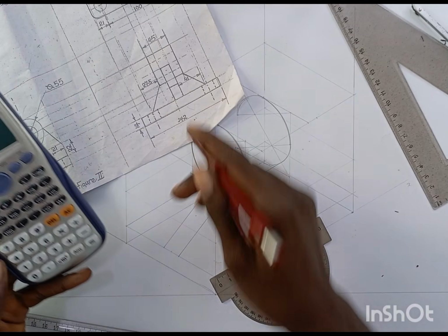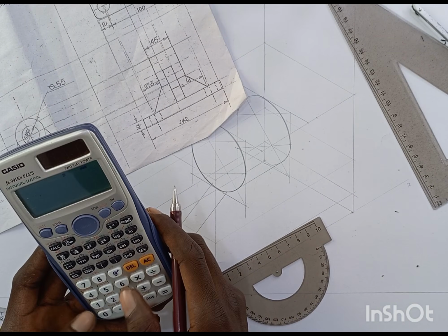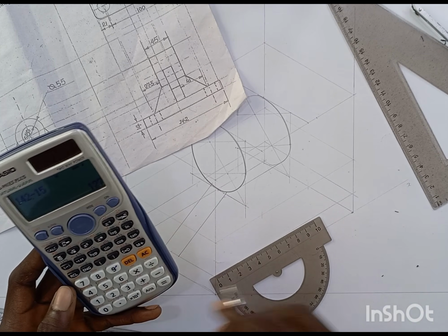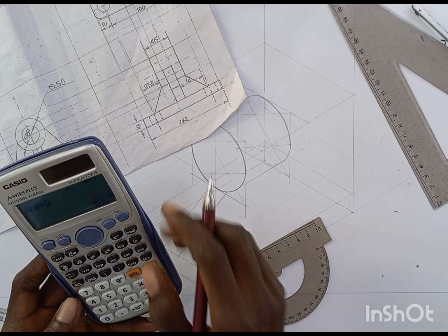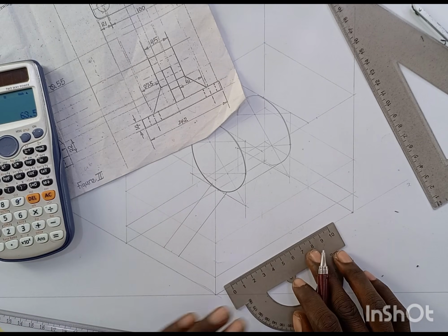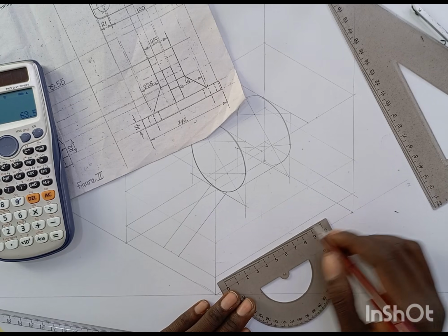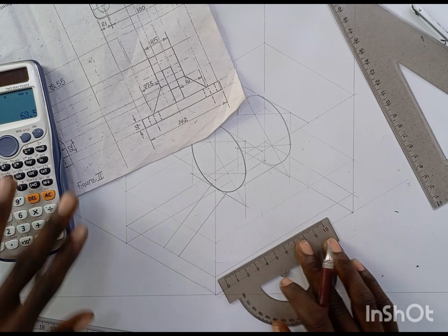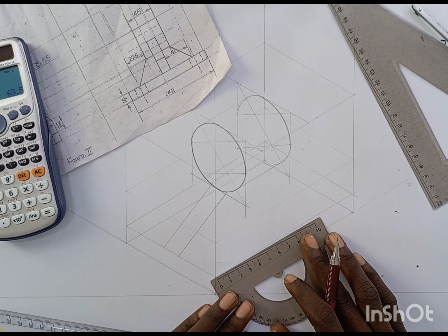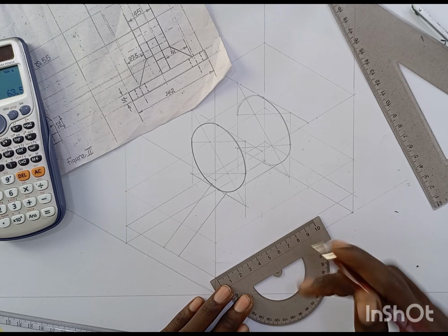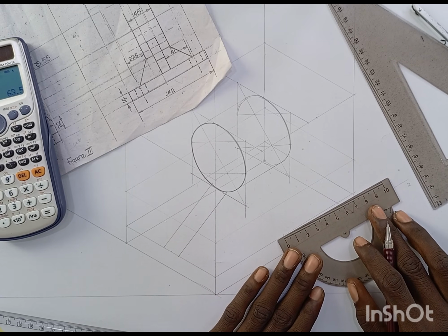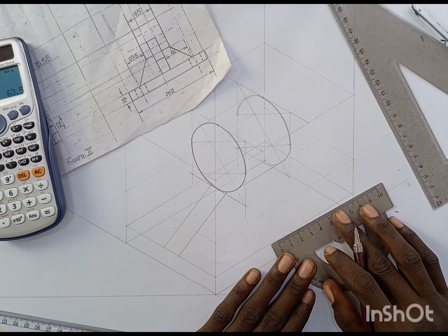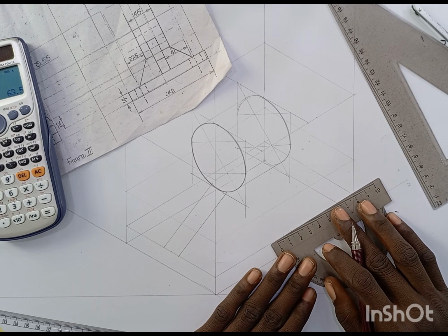Let's use the other method. Let's subtract 15 from 142. 142 minus 15 is 127. Then 127 divided by 2 is equal to 63.5. So you have 2 methods. You can measure 63.5 here, and from here, then you have your center. Or you divide the line into 2 and then take 7.5 across each side. So since we started with 7.5, let's continue with it. So now we measure 71 here. This is my 71. Then I will divide this line into 2, taking 7.5 across each side. 7.5 here. Now I'm going to take another 7.5 from here also.